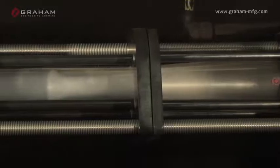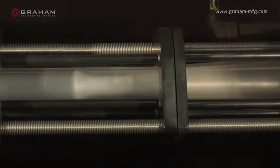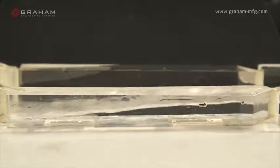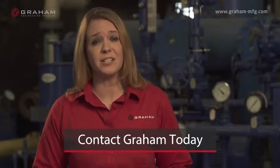Through the glass diffuser, you can visualize the shock wave as the rapid increase in pressure briefly condenses droplets of water. This is the same phenomenon as the sharp increase in water height that was shown on the wavetable. We hope that you now understand the basic components and operating fundamentals of a well-performing ejector. Keep in mind that in order for an ejector to work properly, it has to be correctly sized for your unique operating conditions. Please do not hesitate to contact Graham directly concerning technical and sizing questions.